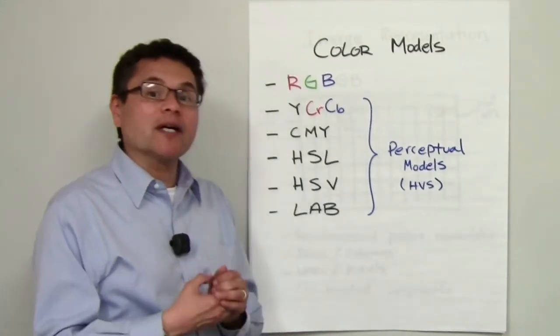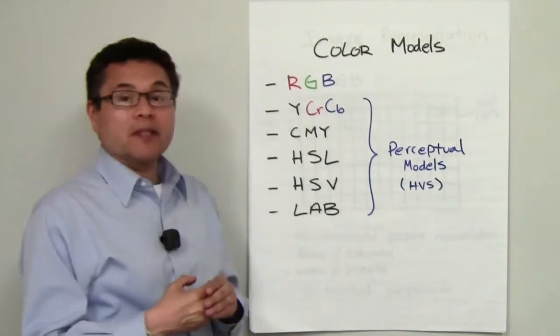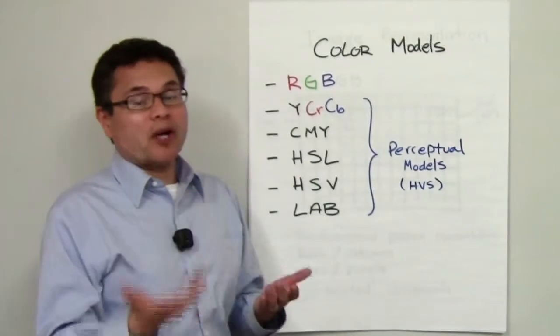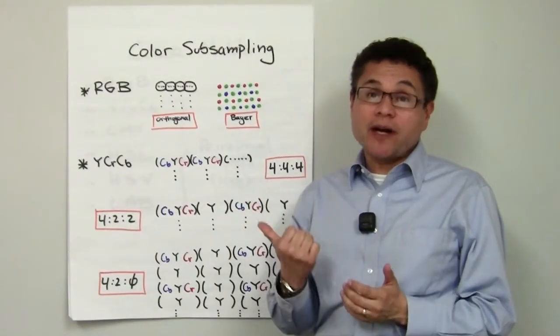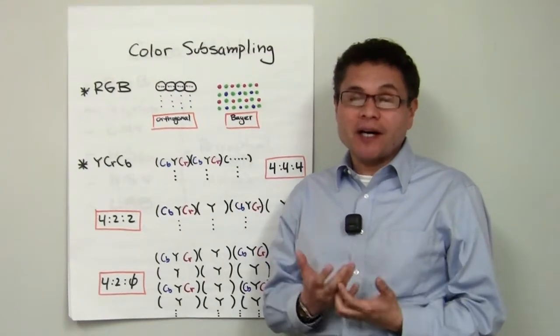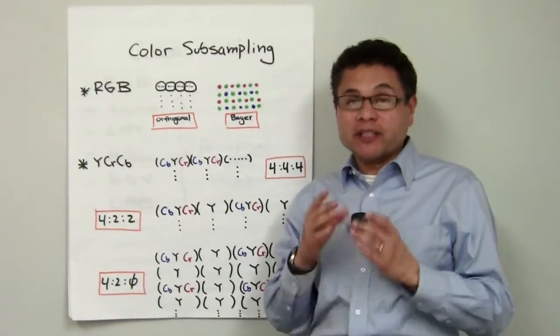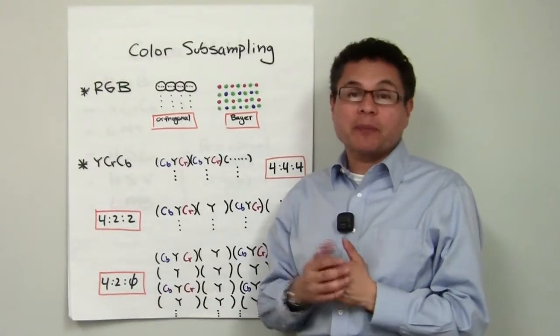And we will see later how it's important to treat those color models, especially when you want to either transmit, store, or process images. As you may recall from the color matching functions graphs that we showed earlier, the response of the human eye to different color primaries is not the same. We are a lot more sensitive to the green spectrum than we are to the blue spectrum.